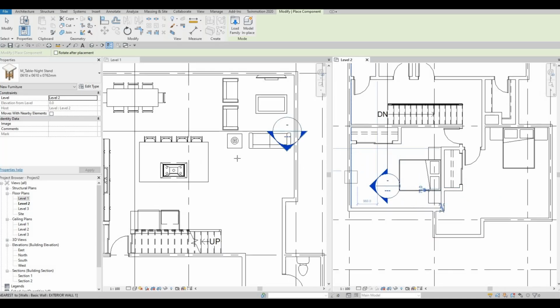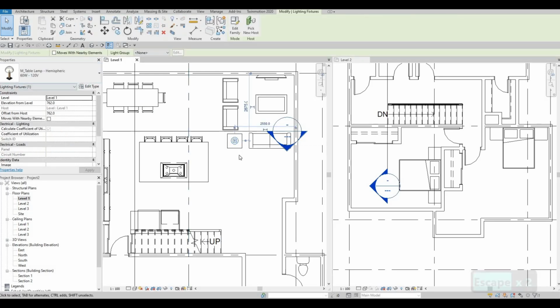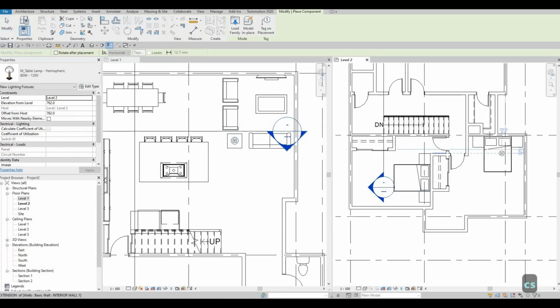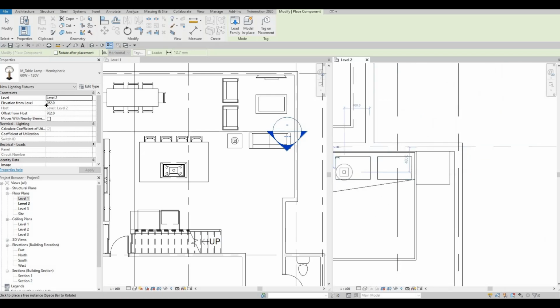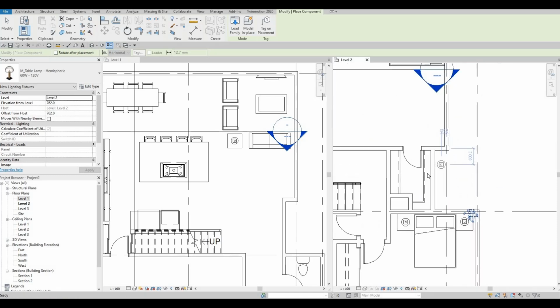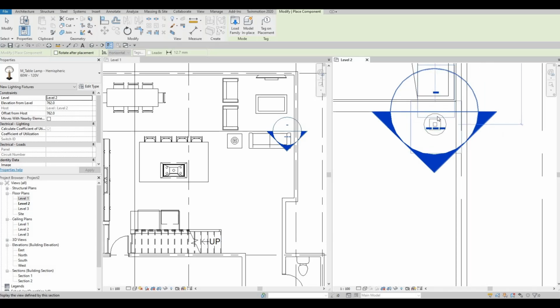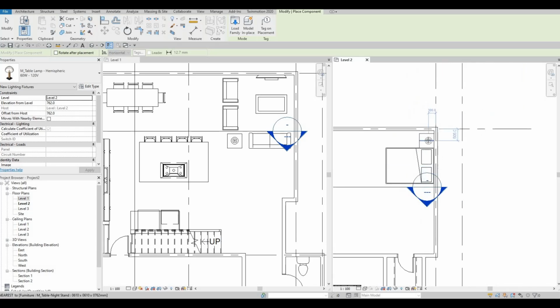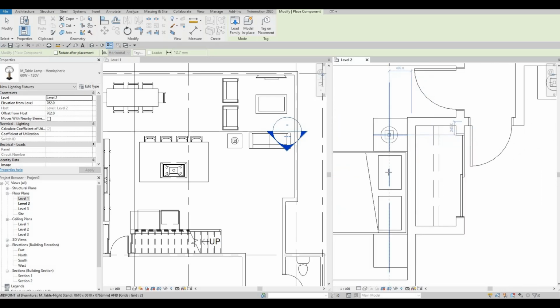Then I'm gonna press escape twice and then click on the lamp, table lamp, CS type, and then now go here, and then you can just add it as well. And it will have the same changes that you did. So we changed the elevation for that. And as you can see, it maintains those parameters. I know we have this one added here. It's not being shown because of this, but we're going to extend that later so that we're seeing everything.